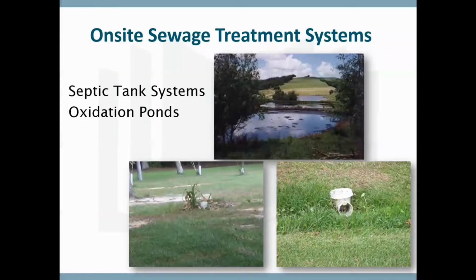And then some other types of on-site sewage treatment systems. There are septic tank systems. Basically, they're somewhat of a combination of a conventional system with some aeration. Sometimes they have a field line, a field absorption line. I think actually my boss at DEQ may have an aerator with a field line and a pipe on the end of that. Basically, it's a method of reducing the effluent. So that's what I mean by septic tank system. But basically, it does the same thing as either an ATU or a conventional system.